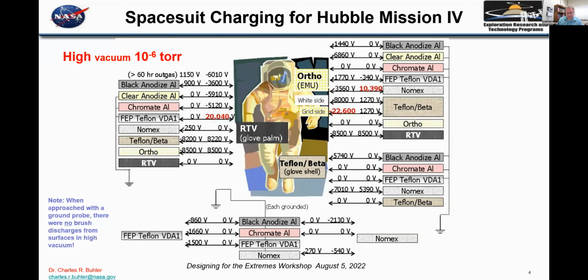As materials contact and separate, they develop electrostatic charge. This happens on Earth every day. When you sit up from your chair, walk across the carpet and touch a doorknob, you get sparks. It's not uncommon to get to 20, 25,000 volts pretty easily due to just triboelectric charging. So what we've done in the past is try to measure some of the fields that come out of triboelectric charging.